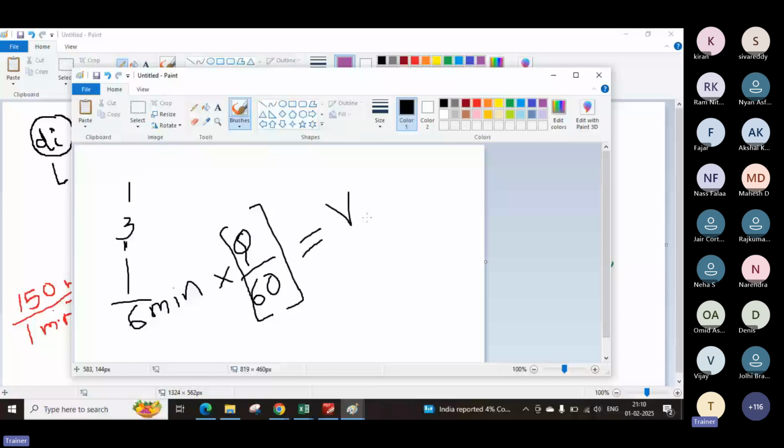So this volume, you know the diameter based on the Vt, the terminal velocity we have estimated. The same diameter we are using. So it is nothing but pi by 4 d square into the h of a liquid.